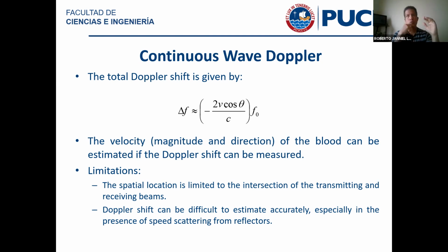Now, the question would be, what type of profile would that be if you assume that the velocity at which the liquid is flowing is low enough, and the diameter of the pipe is big enough? So if you go through all those underlying simplifying assumptions, what type of profile do you expect to observe in the velocity? A parabolic one. Correct, a parabolic one, right?